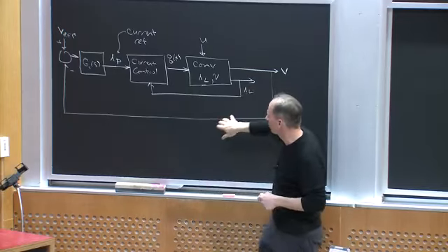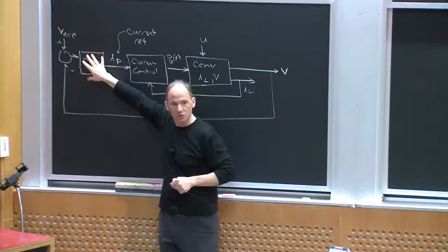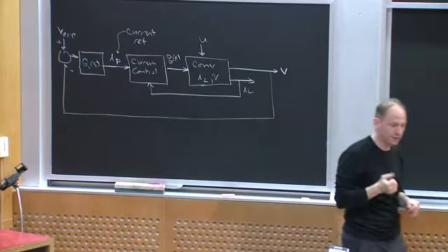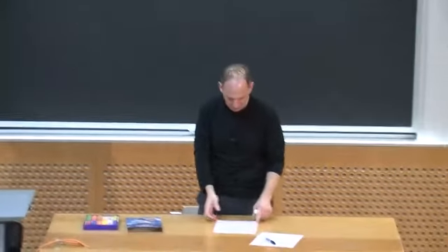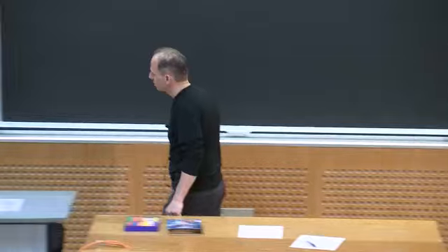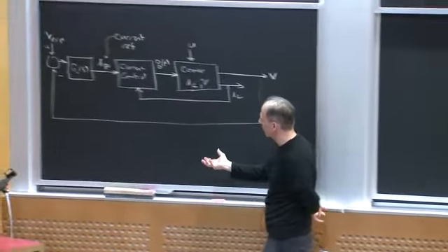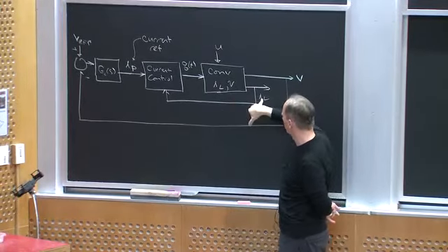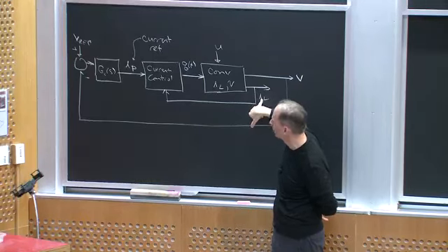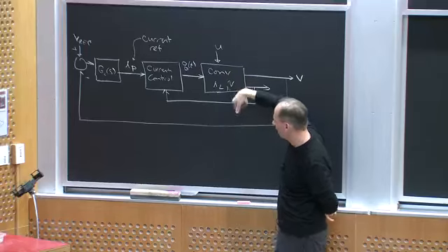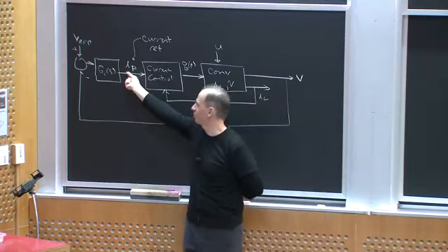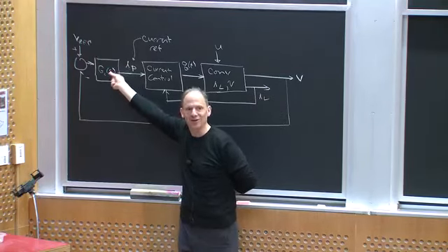In this scheme, that'll still be true of this outer loop control. The inner loop control is actually going to run on a cycle-by-cycle basis, and that has a lot of follow-on benefits. So we're going to come up with a scheme where we turn on the switch every cycle, and then I'm going to turn off the switch based on what the inductor current's doing in a particular way. I'm going to show you the particular way we're going to examine. And so that's going to give us control over what the inductor current's doing. And then I'm going to use my outer loop to control that command to the inductor current.